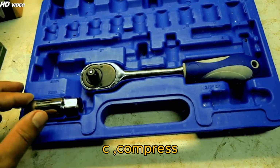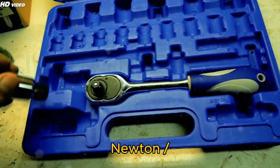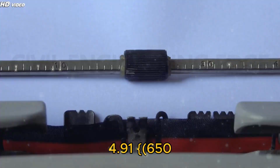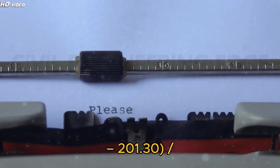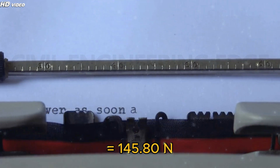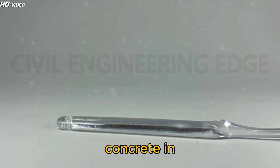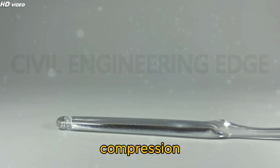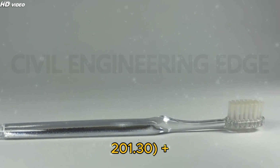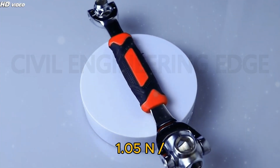300 x 201.30 x C / 2 x 582.90 equals 77,700 x 1,111.30. So C, the compressive stress, equals 4.91 Newton per millimeter squared. Stress in steel equals 13.33 x 4.91 x (650 - 201.30) / 201.30, which equals 145.80 Newton per millimeter squared.